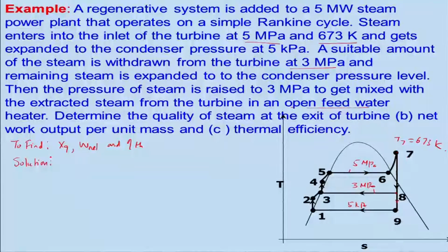Basically, we know this point, because from the superheated steam table at 5 megapascal and 673 Kelvin, I will get the properties.